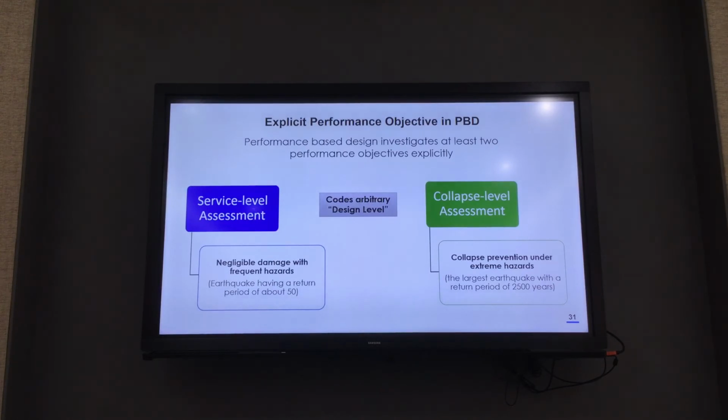You can check that, right? How many people can you pack in this room edge to edge? That will be the extreme case, and you can check for that case that it should not collapse. But no need to multiply the live load by an arbitrary number; we don't even know where that comes from, right?